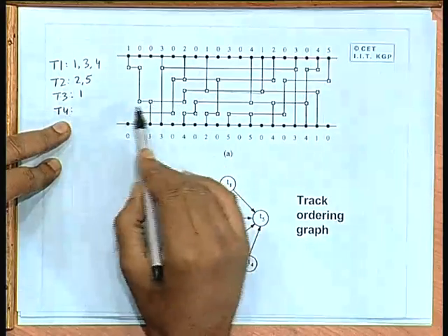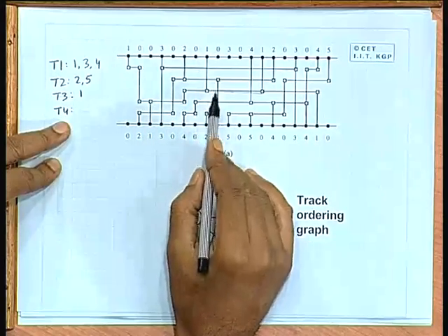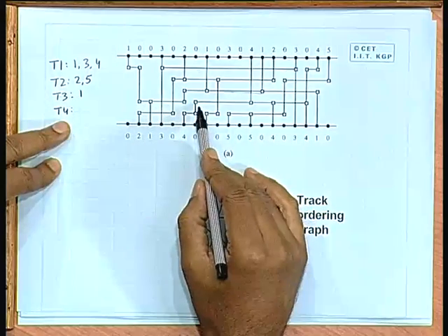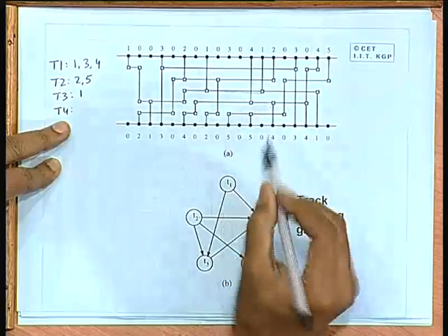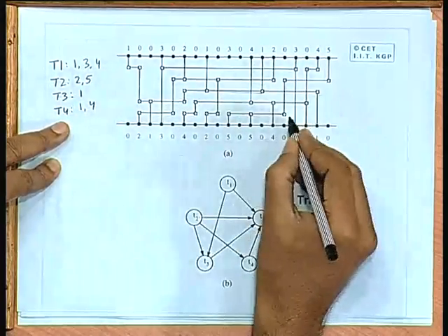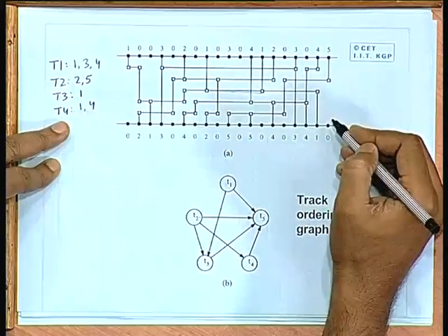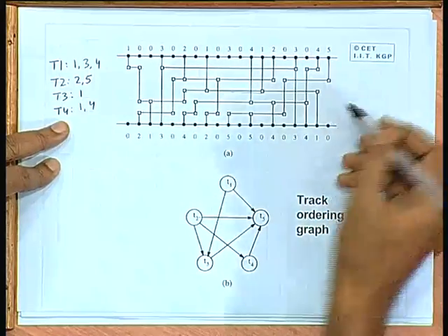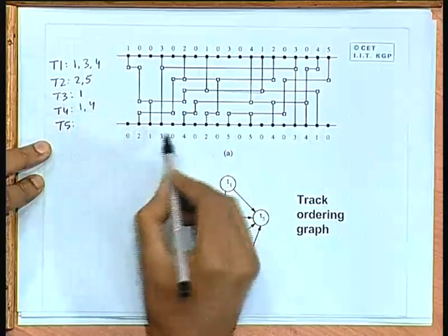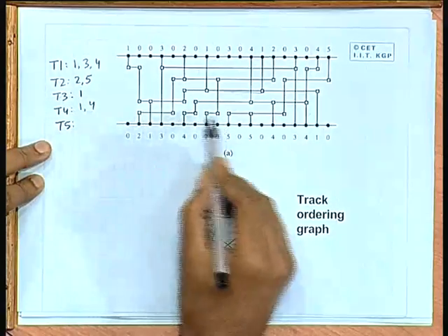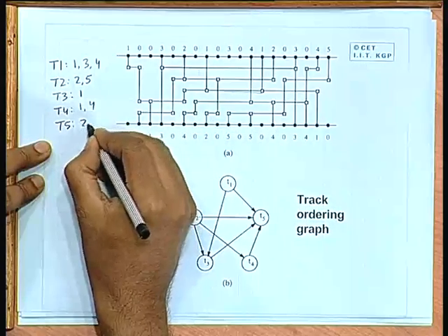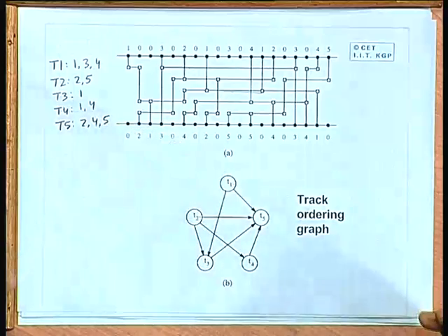Well, here we are considering a 2-layer solution. So, here track 1 is also placed on track 4. So, this is a solution which uses dogleg. This is not necessarily the output of Yoshimura-Kuh, it may be the output of any routing algorithm. There are some doglegs here, so no problem. Track 5, the 5th one, has 2, 4, 5.